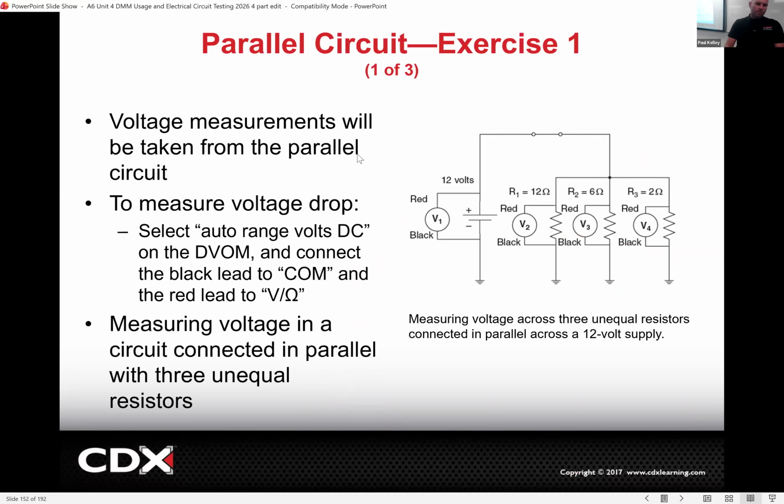All right, so with voltage, I think you'll find this pretty simple. I don't think we'll have to spend a ton of time on it because it's kind of repetitive, right? If we were to do this voltage measurement right here, we got the red, we got the green. So we're measuring voltage across the source. What do you expect across the source? About 12-ish, right? So if we start with a 12, then I were to go over here, this is not available voltage now. This is a voltage drop.